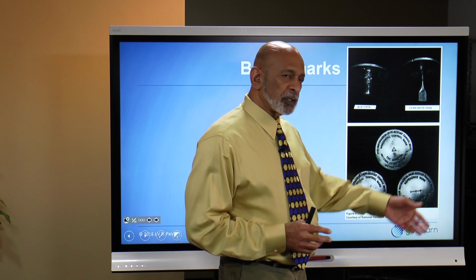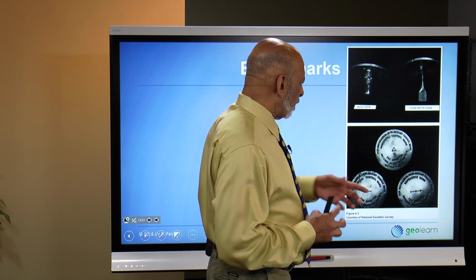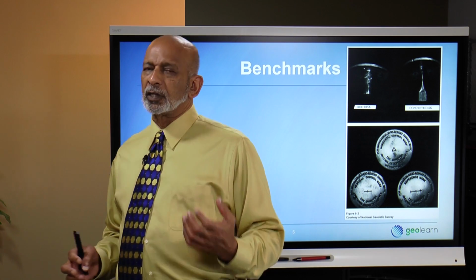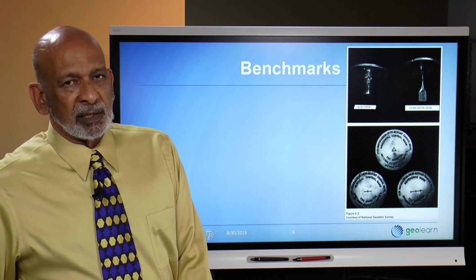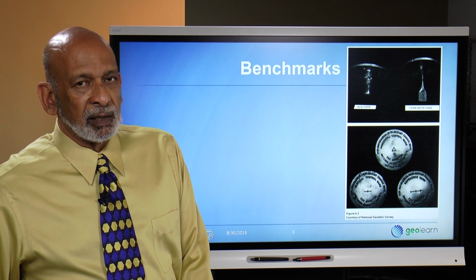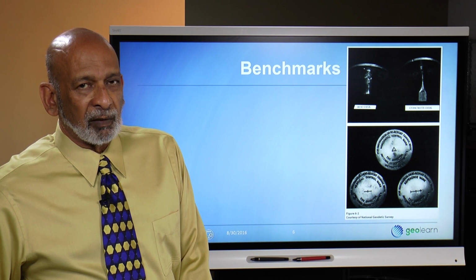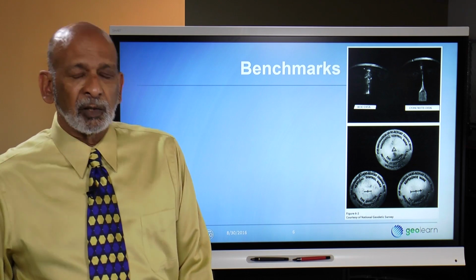This is a reference mark. It may also not have an elevation. But this is called a vertical control mark. And this would actually be a benchmark if it hasn't been disturbed and if NGS has actually done some maintenance on it, and there is a system for going to the National Geodetic Survey to figure out if the particular benchmark is a reliable benchmark that you can use.